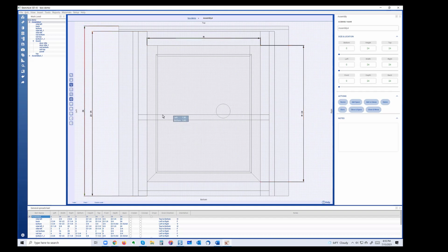The dimensions that I'm going to need. So if I want to know, say, the size between here and the center of that hole, I use the point command. Say, well, that's 12 inches from there, and it is 6.5 inches from there.